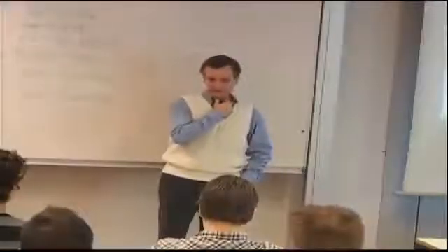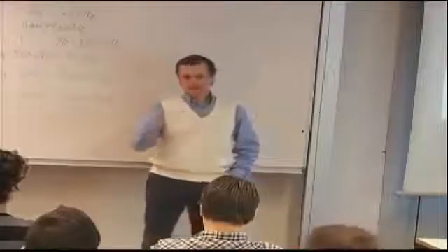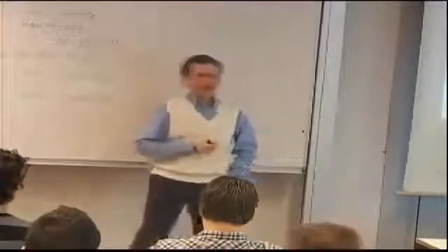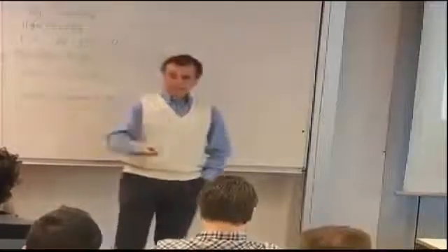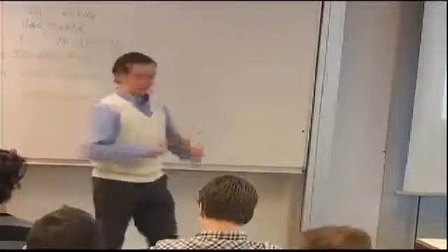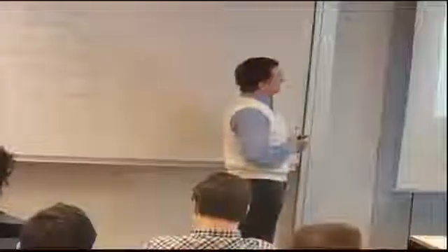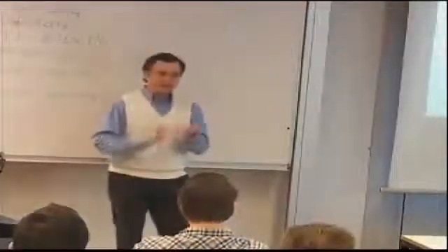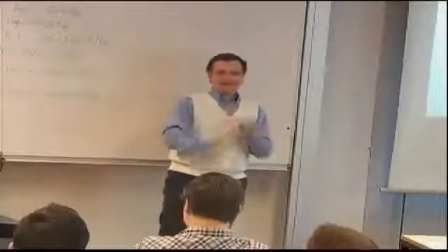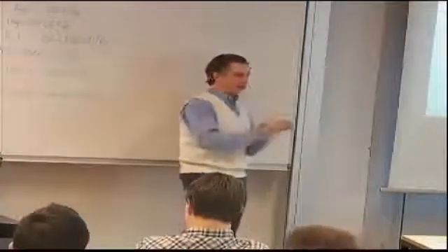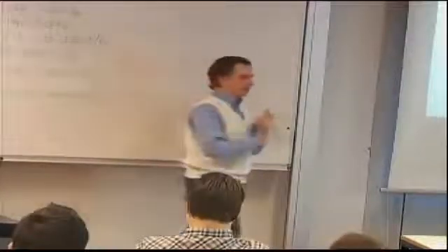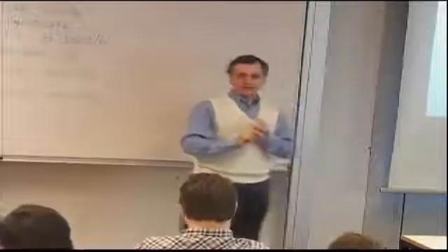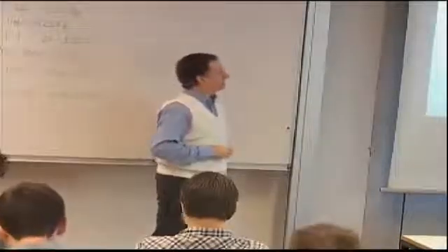and I have to recognize that even if it's pristine and perfect the day I make it, assuming the people on the shop floor were careful enough, which is not necessarily always the truth, then I have to account for the fact that it will be damaged during service, and I don't want it to be withdrawn from service immediately every time there is damage. And I have two types of requirements. One is damage that I can detect and damage that I cannot detect. Because in composites, even damage that we cannot detect, irrespective of the method you use for detection, causes a significant reduction in strength and to some extent also in stiffness.